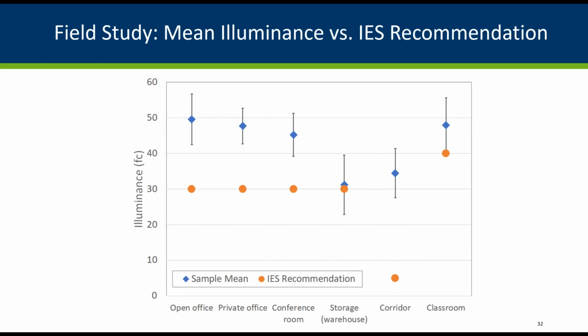The degree to which the LED mean illuminance differs from the IES recommendation is likely due to the nature of LED retrofit projects. These projects traditionally are one-for-one replacements of existing fluorescent lighting due to the prohibitive cost of modifying existing electrical infrastructure and drop ceilings. With little to no flexibility to adjust the fixture spacing, the LED light level is determined by the LED fixture's output.